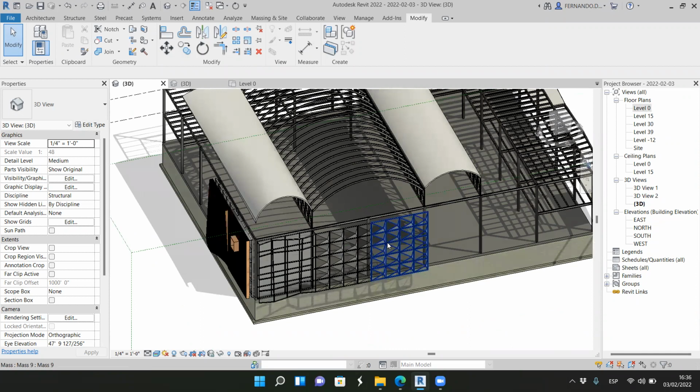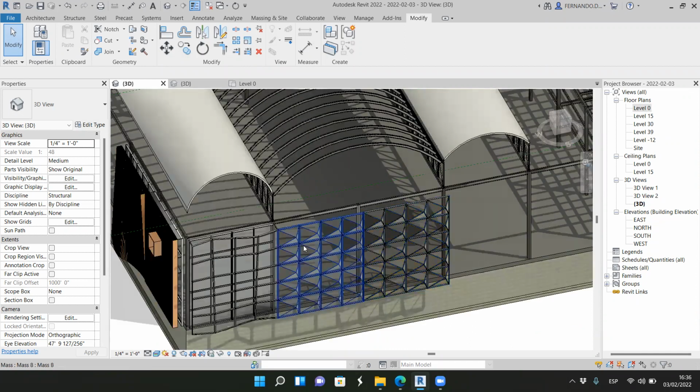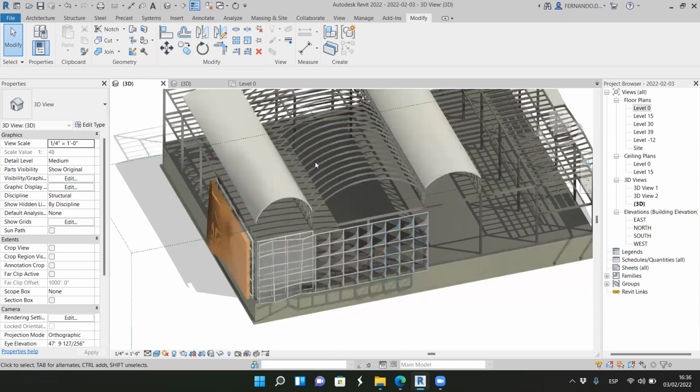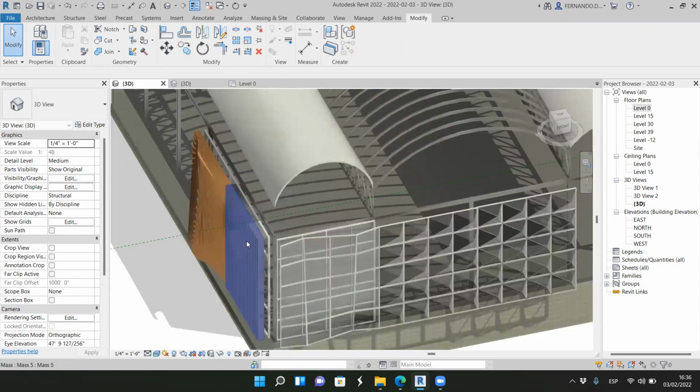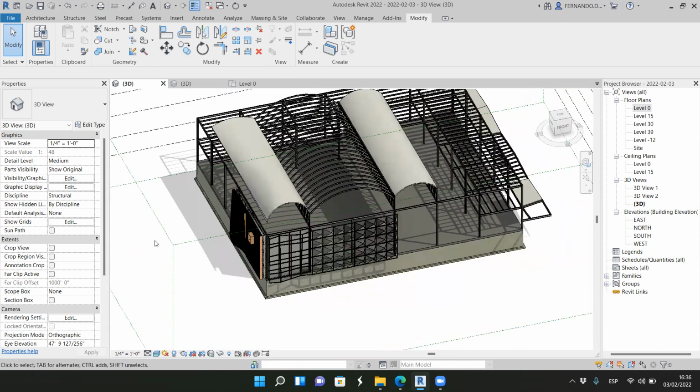This effect of 2 transparent double skins, it works only in the south elevation. It doesn't work in the north elevation, because in the south elevation, we can make the most of the winter sun. For the east and west elevation, I would do something like that. We don't want eastern or western lights inside the building. They are harmful because in winter, basically, we don't have any sun, and in summer, we have a lot of sun heating a lot of hours in the morning and in the afternoon on the western and eastern facades.